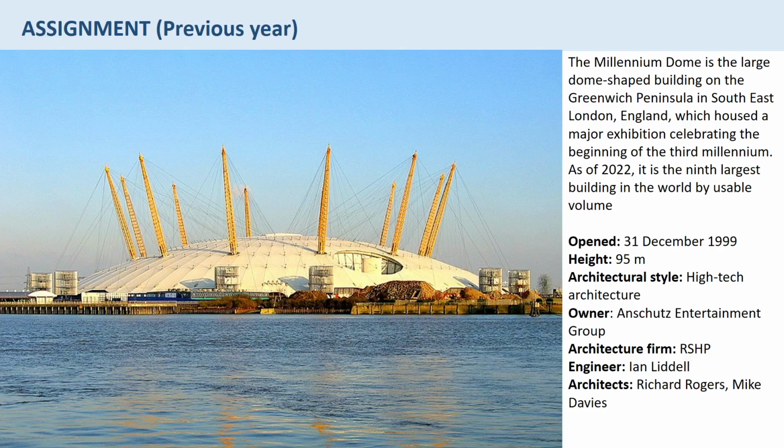Folded plate structures are assemblies of flat plates or slabs inclined in different directions and joined along their longitudinal edges. In this way, the structural system is capable of carrying loads without the need of additional supporting beams along mutual edges. This technique originated in Germany in the 1920s, and it became popular to construct roofs for industrial warehouses and public buildings. Modern folded plate structures are typically made of cast in situ or precast reinforced concrete or steel plate.